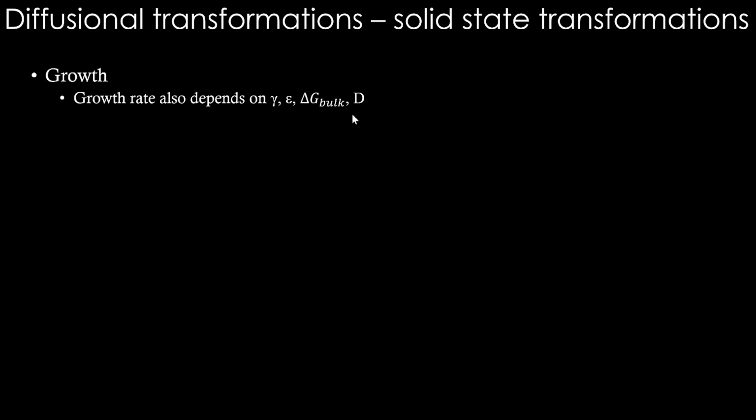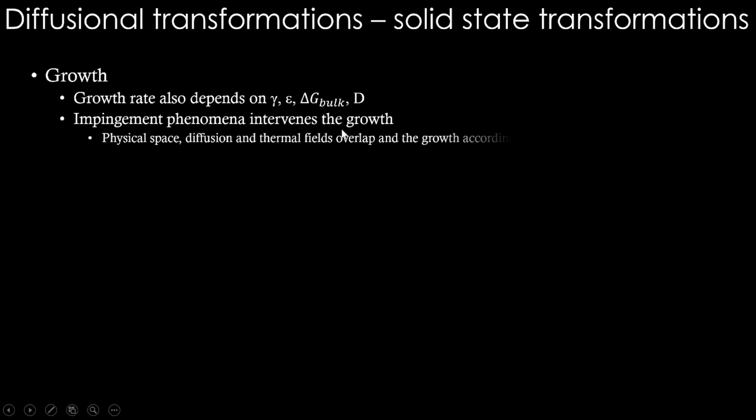So are we done? Are these the things which are going to affect the nucleation and growth? There are more aspects, phenomena such as impingement. It intervenes in the growth. What is this impingement? It is this physical space, diffusion and thermal fields. Diffusion fields and thermal fields overlap and the growth accordingly changes.